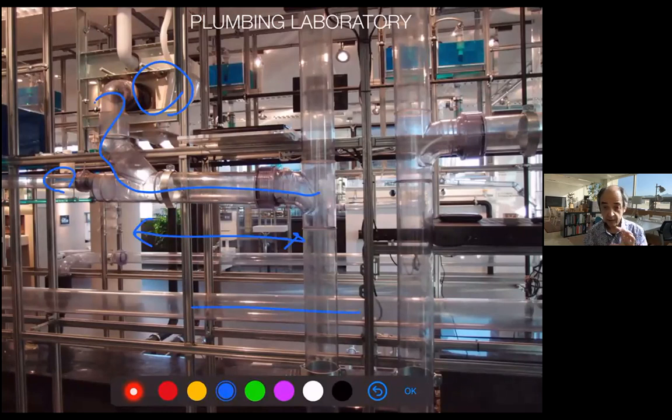Only one comment from this site. When I studied, I was told that in the sewage, especially those long elements, the bigger the diameter, the better, otherwise it clogs. But experimentally, the opposite is true, because if you have some kind of deposit and the diameter is very big, the water goes through and you just increase the sediments, right?